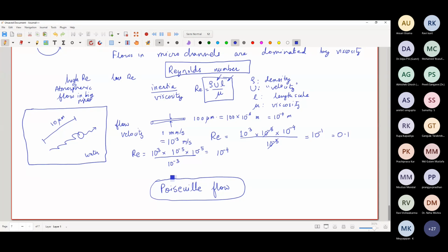But yes, the stress tensor does comprise, broadly speaking, the viscous stresses, and the viscous stresses in this case depend on the viscosity, of course, and the deformation tensor, which depends on the gradients of velocity.